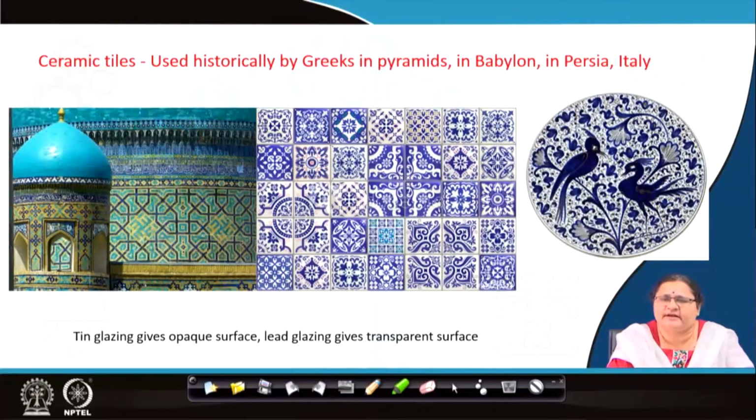If you remember when we studied terracotta, either glass was ground and mixed with the clay, or else glass was put in the furnace. So, glass actually was fumed and the fumes were getting coated on top of terracotta, giving it a kind of impervious coating. If you remember the term impervious, water absorption will be minimal. So, its long life will be assured.